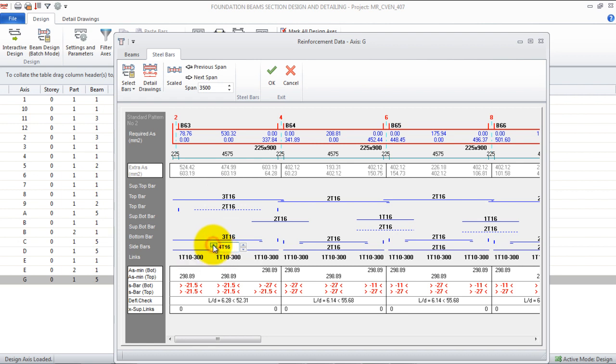I'm going to make 4 at the bottom, 3 on each span to make the beam. Okay, against deflection, I can see deflection is satisfied. So I'm going to make this 4. We'll make this 3, this one 3, 3 top, 3 bottom, the side has to be 4.